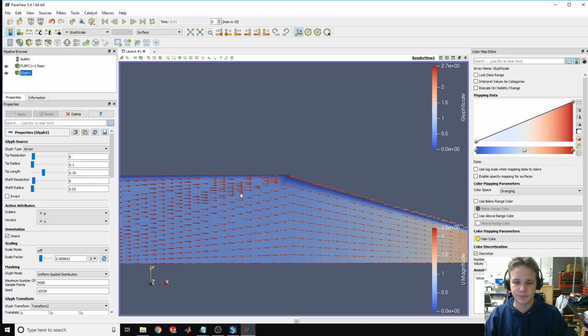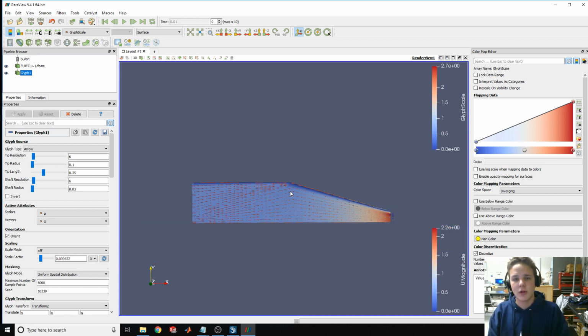So, and you're definitely not losing a lot of momentum to the wall. It's kind of more linear, and in any kind of design, if you want to get to this end speed, yeah, you want to start with a gradual cross-sectional area decrease, not just a flat face. Water does not like flat faces. Any flow does not like flat faces.